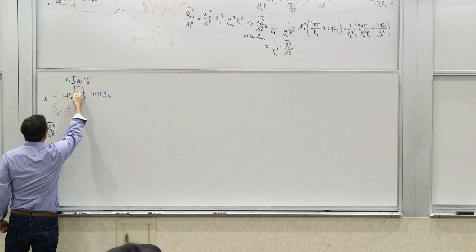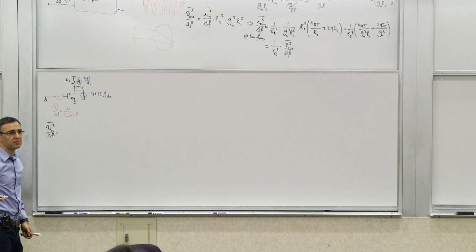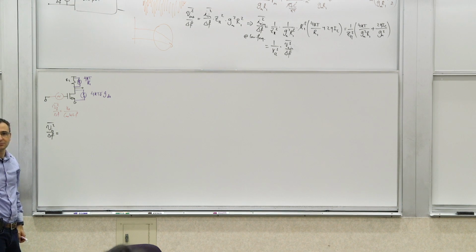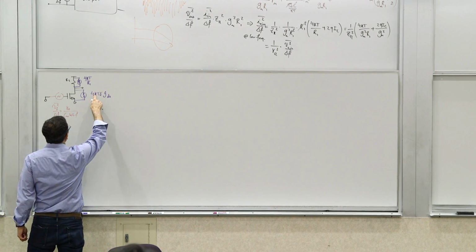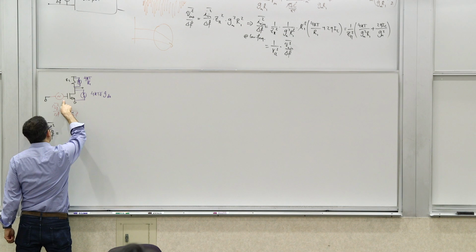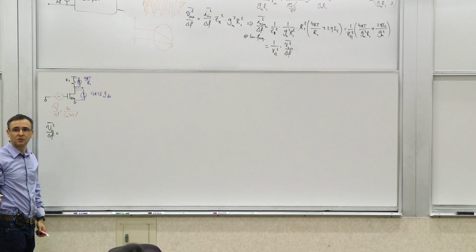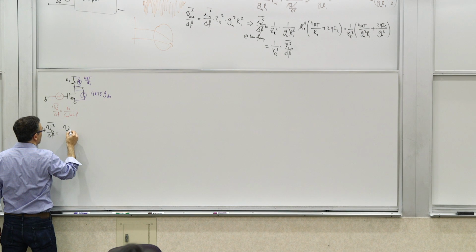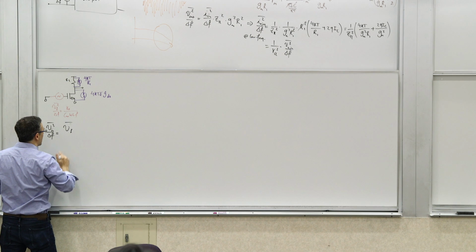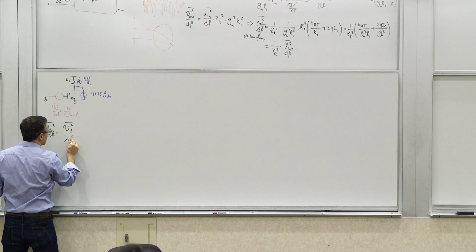Well, we know that these three sources are uncorrelated. They're generated by different physical phenomena, or at least physical phenomena at different places. And okay, so this one is already at the input. So we know it's going to be there anyway. So it's a superposition. And since they're uncorrelated, you add the power spectral density of each one of them. So you get Vf magnitude squared over delta F plus